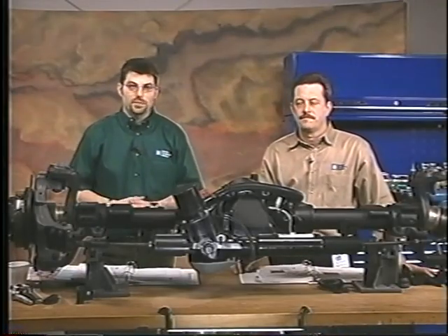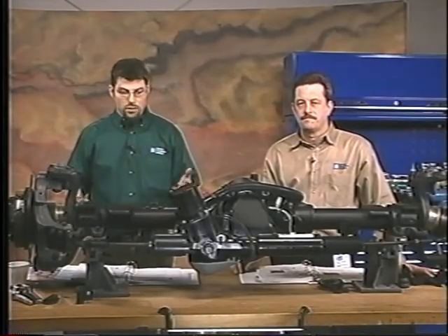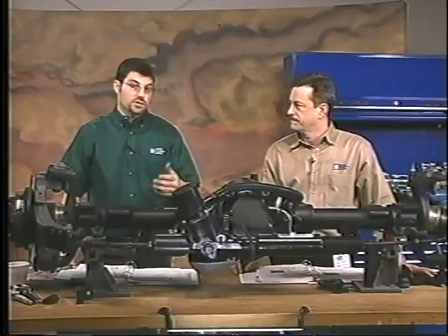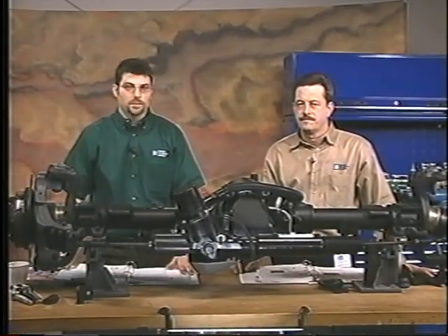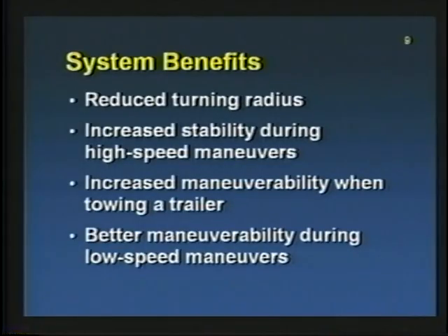So first, the system benefits. You can imagine a vehicle equipped with rear wheel steering in addition to front wheel steering gives us benefits and advantages over a typical vehicle with conventional front wheel steering. Some of these include a reduced, or smaller, turning radius, increased stability during high-speed maneuvers, increased maneuverability when towing a trailer, and better maneuverability during low-speed maneuvers, much like parking lot maneuvers.